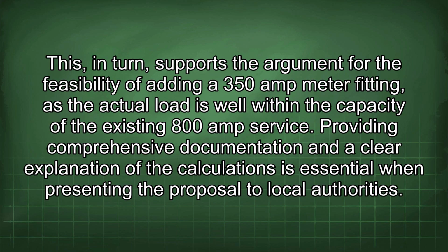This, in turn, supports the argument for the feasibility of adding a 350 amp meter fitting, as the actual load is well within the capacity of the existing 800 amp service. Providing comprehensive documentation and a clear explanation of the calculations is essential when presenting the proposal to local authorities.